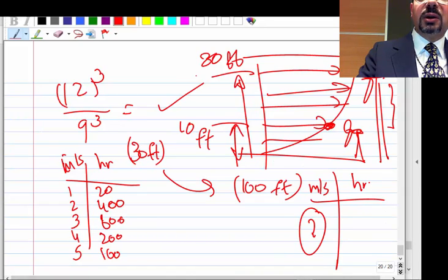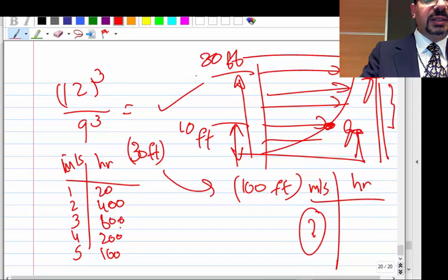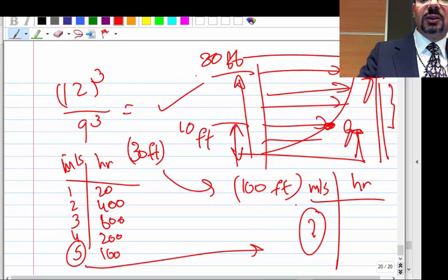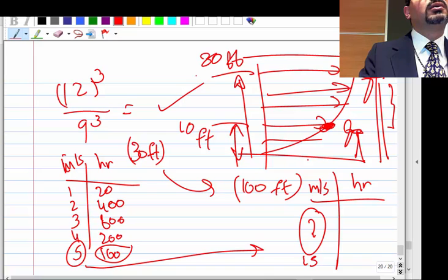But will I get the same hour distribution? Let's say I'll show you how we turn this 5 meters per second into, let's call it, 15 meters per second. If it's 5 meters per second at that height for 100 hours per year, and the calculation in the next slide tells us that when it's 5 there, it will be 15 up there, how many hours will it be 15?